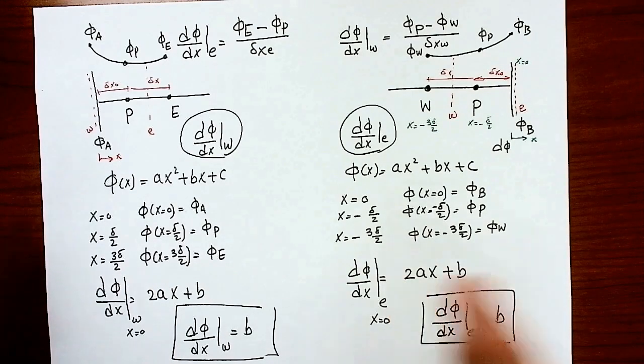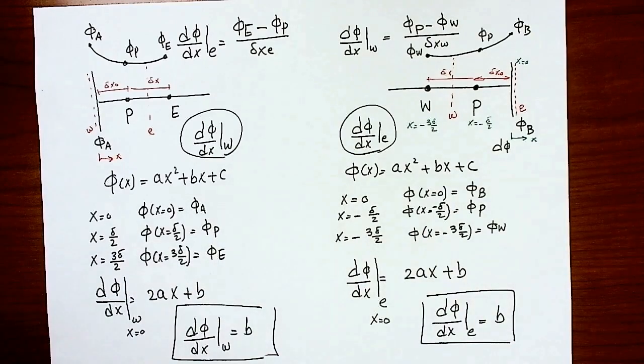That's for the diffusion term near the boundaries. And the second difference is how we approximate the diffusion term by phi face for the east and west ones. So that concludes the QUICK scheme.